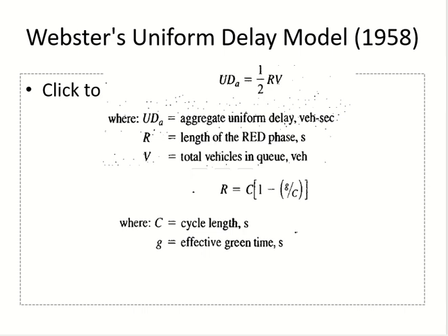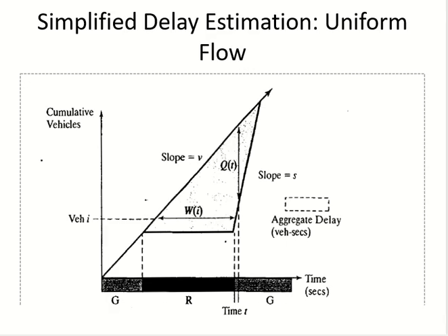Yeah, in the cube, yes. We can calculate vehicles which are in the cube in two ways. Okay, you see this graph over here? The slope, which is V or S, is the flow, right? Vehicles per unit time. If I multiply the flow with time, I get the number of vehicles. Which vehicles do I want? The vehicles which are in the cube.